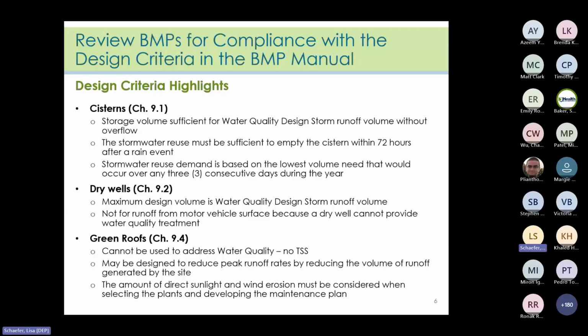Dry wells. The design of a dry well cannot exceed the runoff volume from the water quality design storm. Although a dry well cannot be used to treat runoff from motor vehicle surfaces, it can prevent clean roof runoff from being commingled with the dirty runoff from motor vehicle surfaces, such as a driveway, and it can therefore reduce the size of a BMP needed for water quality treatment.